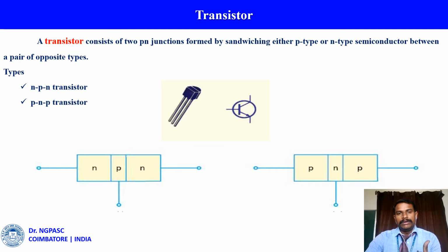In each type of transistor there are two major junctions, so these are two p-n junctions. Therefore, a transistor may be regarded as a combination of two diodes connected back to back. There are three terminals, one taken from each type of semiconductor. The middle section is a very thin layer. This is the most important factor in the function of a transistor.